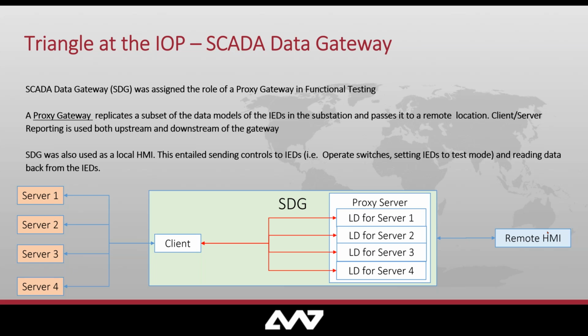And the third point I had, I'm just rereading what I had. Okay, also the third point, from an engineering perspective in SCL, if you had direct communication to the substations with 61850, that would create one huge SCL project, or at least you would need a lot of SCD files exchanged. So from an engineering perspective, it's also creating a certain separation. Having said that, there are some discussions going on from some people who see that in the future we may not need that gateway and can talk directly.